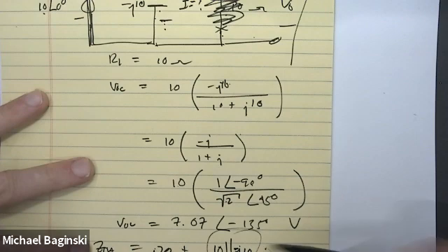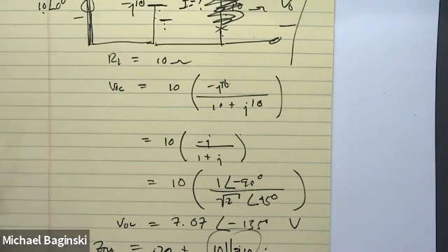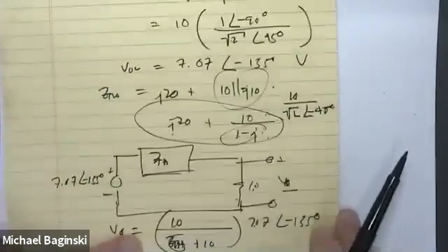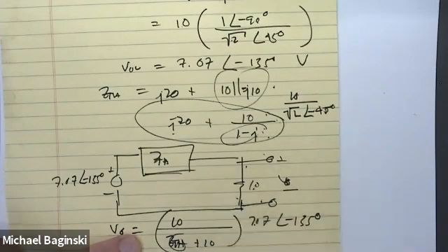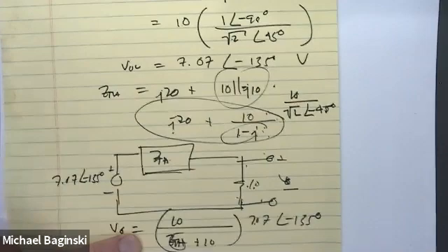That's Z Thevenin. There's no voltage division here. Oh, the voltage division here? Here's what I'm doing. If you want the voltage here, I take this value, the load impedance, and then I divide it by this plus this, because there's only two elements. Is that what you're talking about?